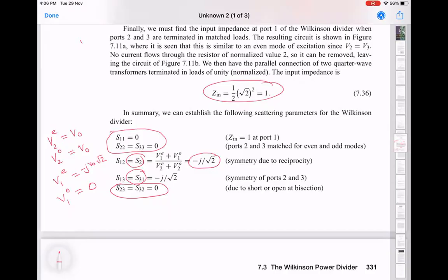Just to give an example, one of my students who graduated recently, Sumeru, applied this even odd mode analysis to this circuit, which we call the ring coupler. It's a circular thing with 2 ports, and so it again has an axis of symmetry. So using that, he was able to analytically work out some formulas, which again gave us intuition of why this circuit works. We knew already from Microwave Office simulations that the circuit was doing something very interesting. Just to have a deeper understanding of why it is doing what it's doing came from doing the analytics.